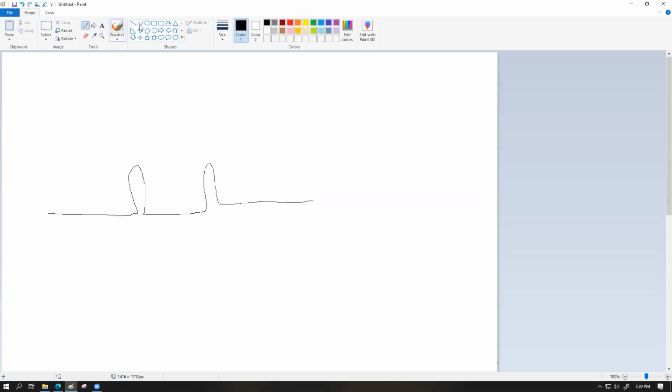And in these loops, let's say this is a continuous string, and these loops are made by tying with a small piece of string at these points, and we are pulling this thing on opposite sides. Now, what's going to happen? As long as these binders can hold themselves together, we are applying force on two opposite sides. As long as these two binders can hold them together, there will be a continuous force along this line. Let's say at some point in this pulling process, this binder vanishes altogether. So if this does not exist, there will be a sudden drop of force and a significant elongation.